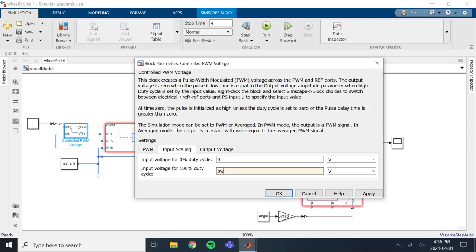So in that case, we're going to have PWM volts, that's 5 volts. What's going to happen is if we feed 5 volts into this reference point, it's going to send out a PWM signal of duty cycle 100. Because it's on average mode, it's going to send in basically a 5 volt source. If we changed our reference input to 2.5, we're going to get 2.5 on this end.